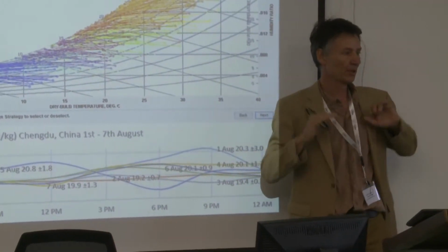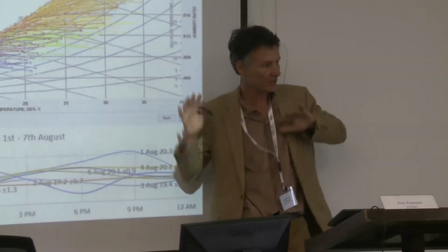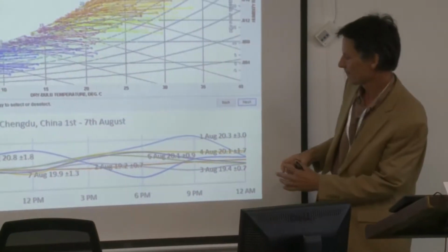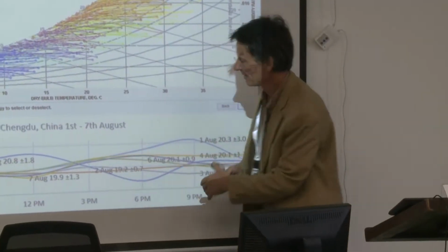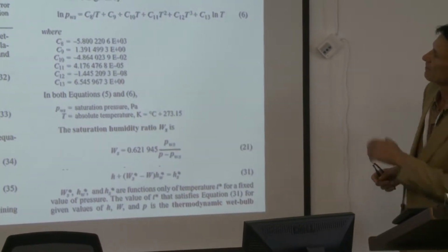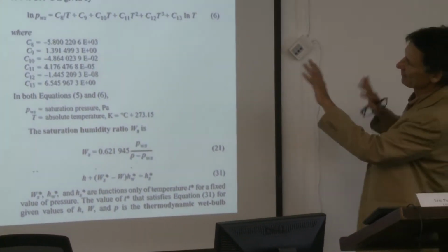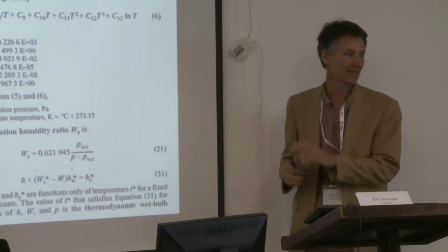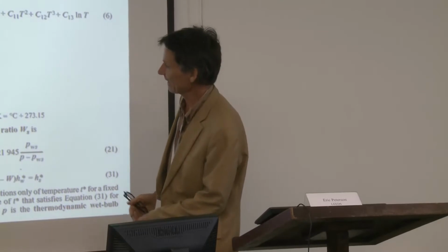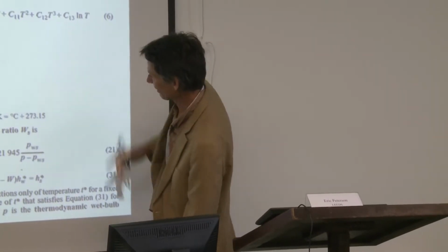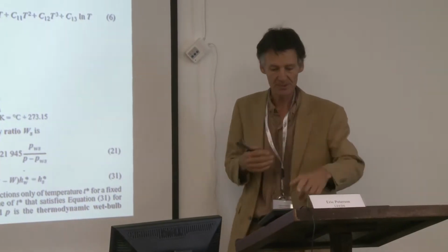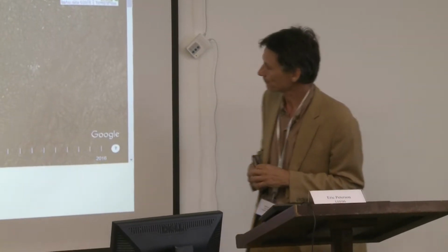I guess there's a buildup of afternoon thunderstorms during the day. There's evaporation going on. But still, it's only a fractional variation through the time of day. So I'm just trying to support my argument that this daily data set is useful. I just wanted to give you a taste of converting this stuff around. It's highly nonlinear. The Handbook of Fundamentals psychrometrics chapter shows you it's a lot of nonlinear stuff. You've got to iterate around. You've got to have an algorithm to calculate what's going on between wet bulbs and dew points and so forth.